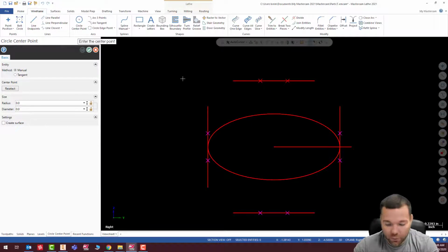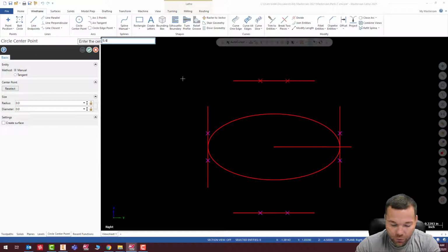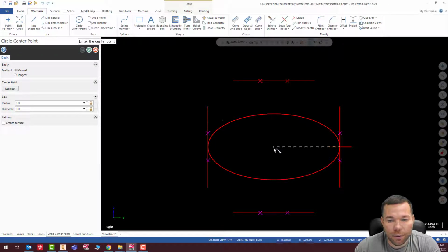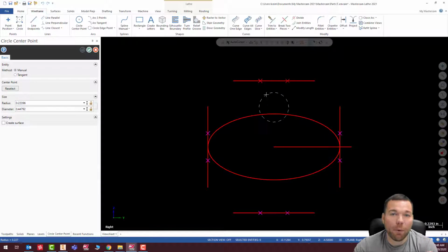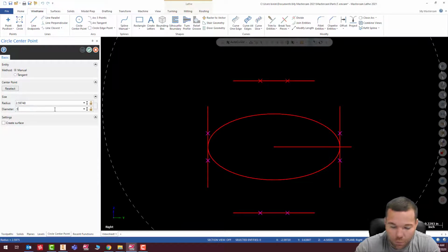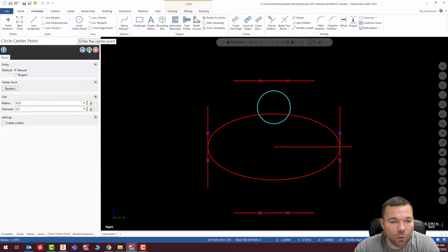So go ahead and pick this. I'm going to go 0, comma, 0.6, comma, enter. Okay, let's try that again. 0, comma, 0.6, comma, enter. Oh, because I put a comma. I'm an idiot. Let me try that again. 0, comma, 0.6, enter. There we go. If I put a comma after my y-axis, then it's expecting a z value, and it will just error out. So just a small mistake there on my part. 0.25. So there is our circle.